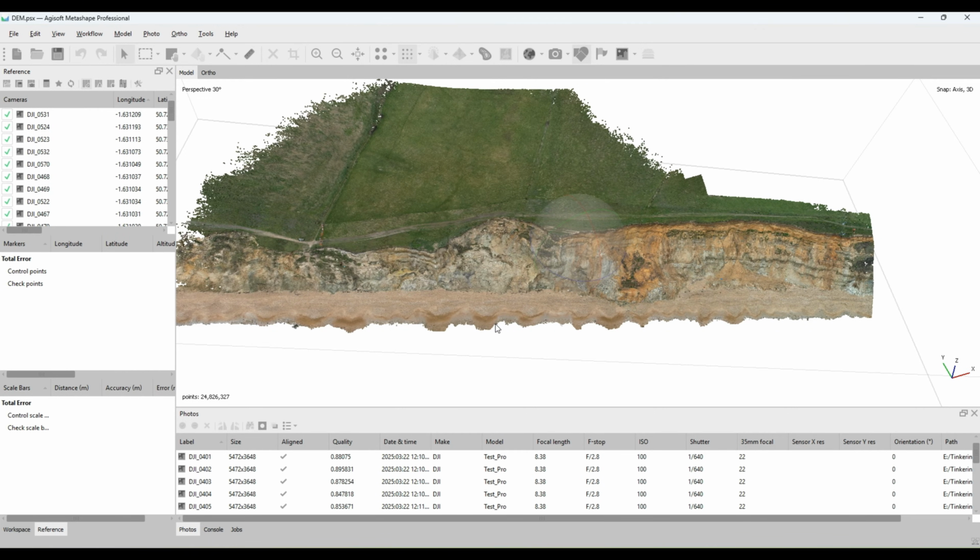So we're ready now to jump to our next step, which is going to be building the mesh itself. I usually like to generate the DEM and ortho imagery before I ever jump into building mesh and textures, things like that. And that's just from a work point of view. In large civil engineering projects, a lot of the aerial survey data that we deal with is ortho imagery and DEM data. Particularly when we pop it into GIS platforms and, certainly from the DEM data, start extracting topographic information from that. We do volumetrics.